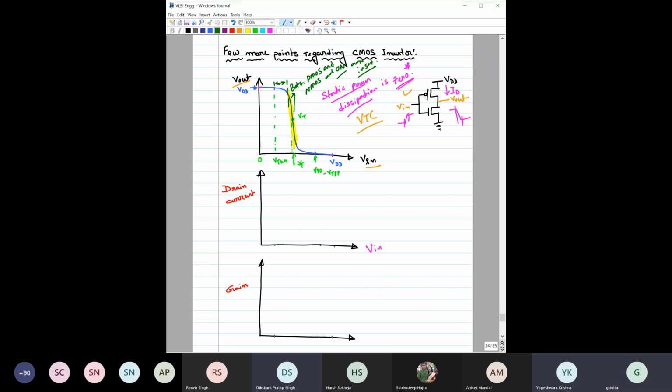No, sir. Yes, but lower. See, because only for this region the NMOS is off. Only for this region the PMOS is off, right? Other than this region, PMOS is on completely. Again, outside from here till this point, in all regions NMOS is on.